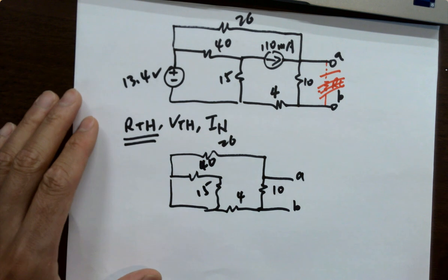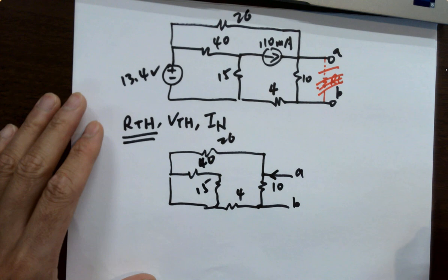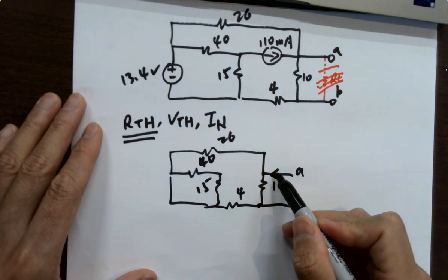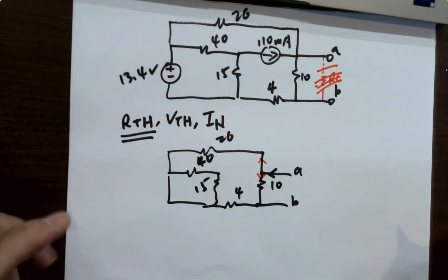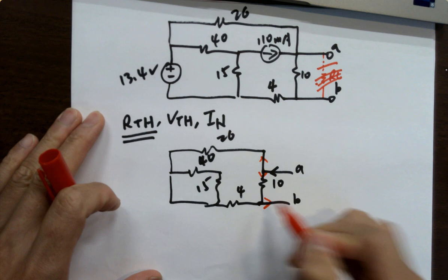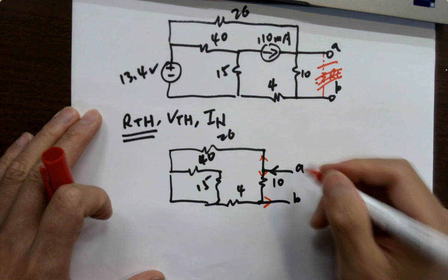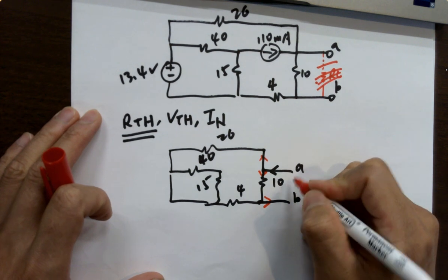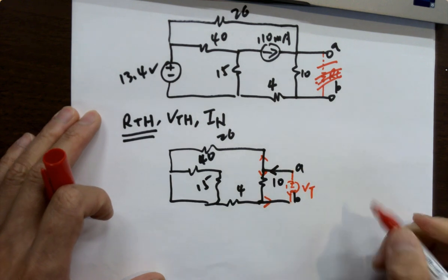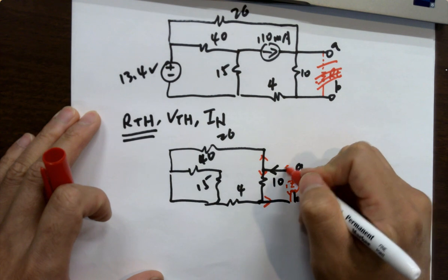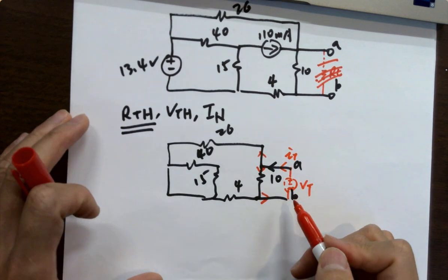Okay? So imagine that you have a little current being injected into the node over here. So it's being split into two branches, right? 10 ohms directly goes back to B. Usually I don't want to assume too many variables. So basically, if you assume there's a V-test, this current is going to provide an I-test over here, and that I-test eventually will go back to the cathode of the voltage source, right?